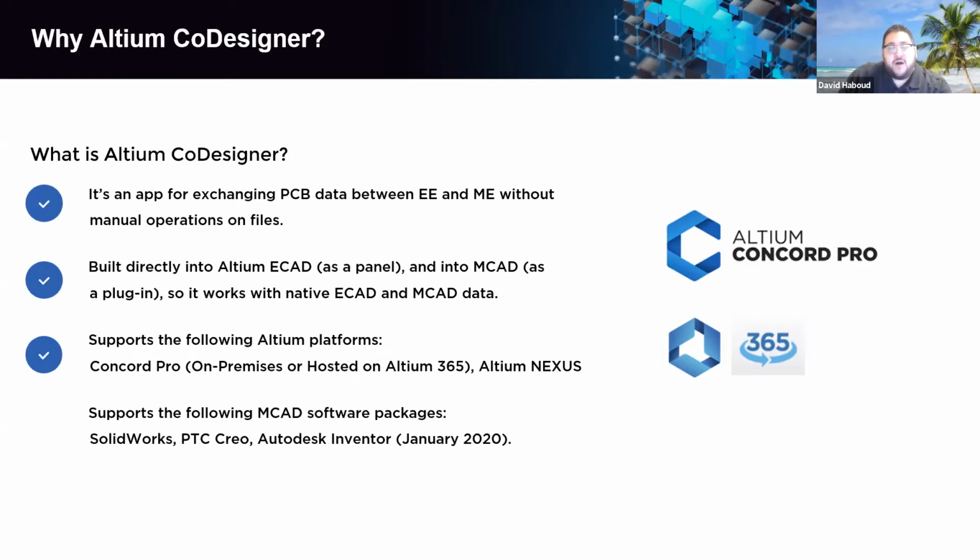Currently, PTC Creo and Autodesk Inventor do not need any additional licensing to have that interaction. Our partnership with SolidWorks requires an additional purchase of the PCB connector license. Depending on who you're working with, some of the resellers are a little bit confused on that, but it is the PCB connector license, not the MCAD CoDesigner license, which is another separate product that is its own standalone thing.